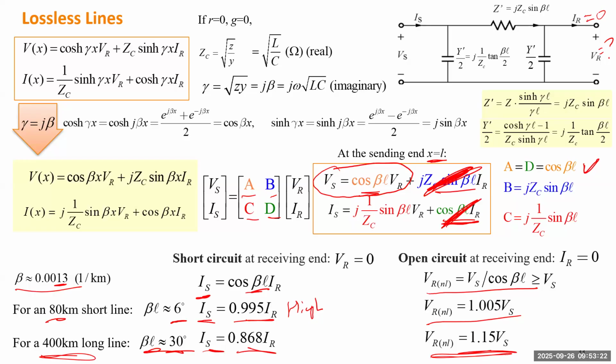So which means if I have a 500 kV line, 5% times 500 will be 25 kV. So you want to operate at 475 to 525 kV, within 5%. But if you go to 15%, that's like a 75 kV difference compared to the nominal value. So when you open the circuit for a long line, that can be a big problem. This can be a really big concern.